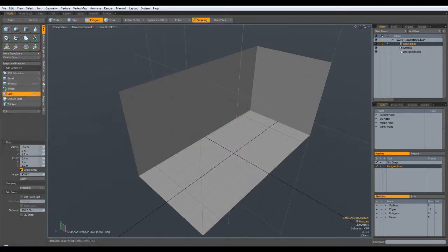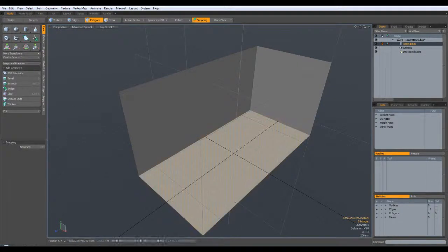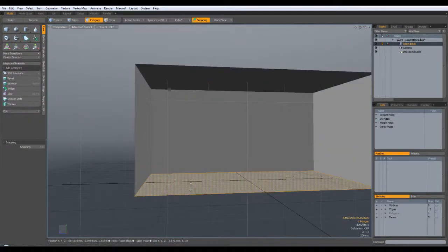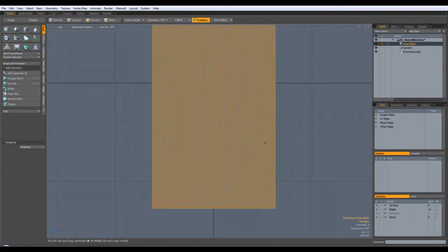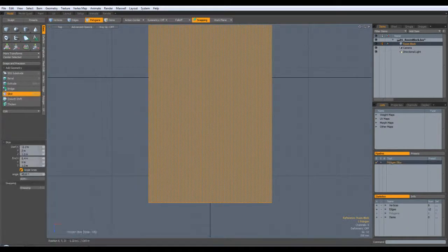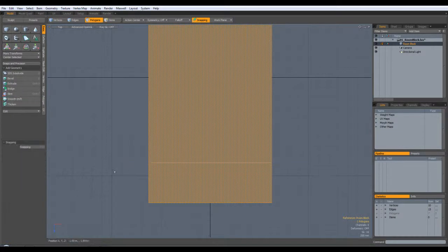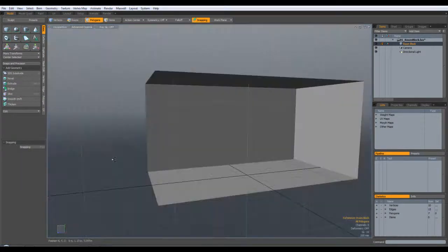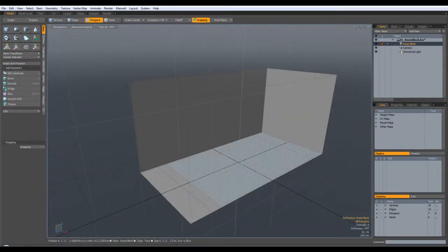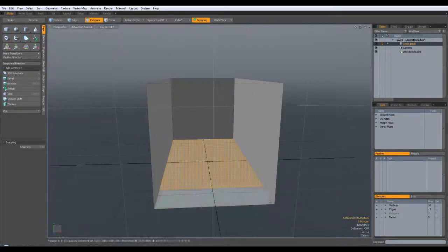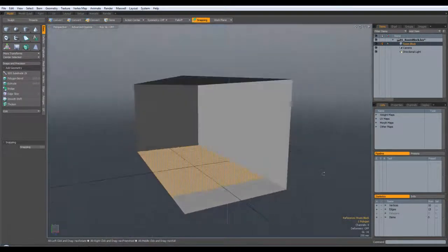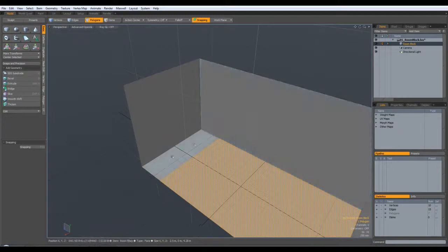Alternatively, say we just wanted to not cut these walls, just cut this bottom plane. If we select that bottom poly there, and then go straight back over to top view, no difference, and we cut across there. Spacebar, drop the tool. Now when you come over, you can see it's only divided those up, and these others are still solid there.